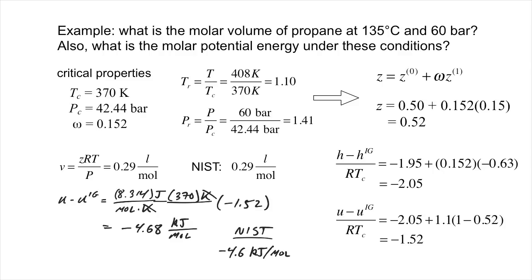What I hope these examples illustrate is that although it's hard to predict thermodynamic properties of real substances from molecular properties alone, the principle of corresponding states allows us to leverage our qualitative understanding of what's happening on the molecular level to make some amazingly accurate predictions extrapolated from just a few key data points. As we'll see next week, by combining equations of state with first law analysis, we can fully map out the relationship of internal energy of a real substance to other intensive properties, including an accounting of potential versus kinetic energy.